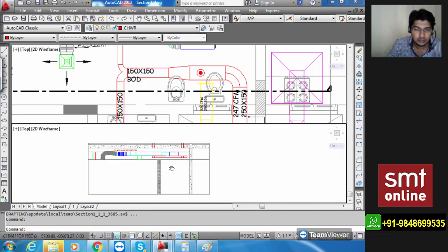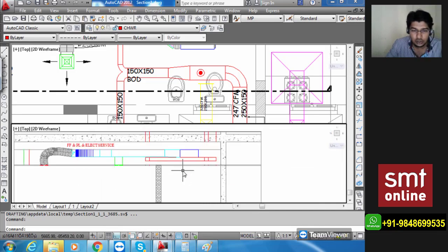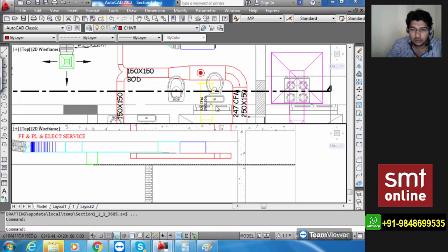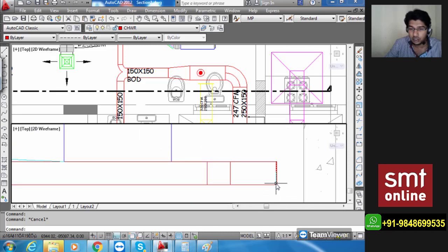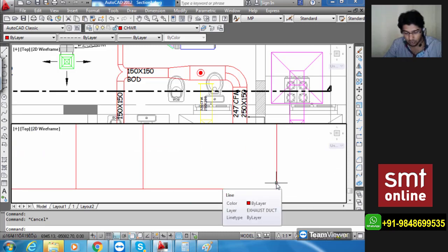We can clean that up a little later. So this is the exhaust duct that we have. It is also done. Now you see, if I'm going to click this side and I'm going to click this side, this is where before we ended from the last portion you have the turning point, and after that we cannot see where it is turning to because we are not in that section. So we have to draw the same turning point once again.